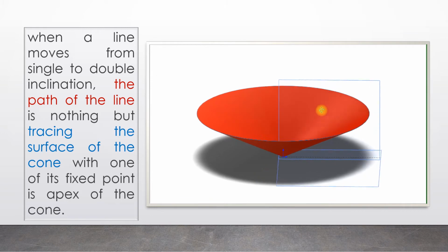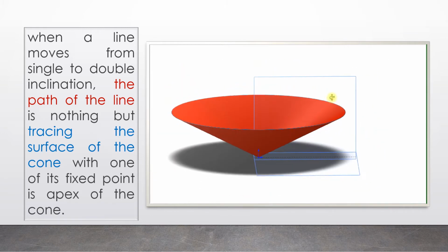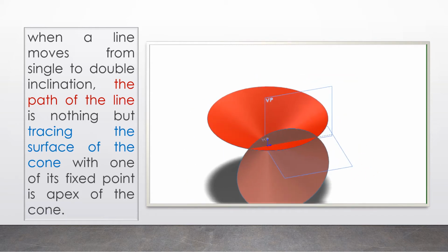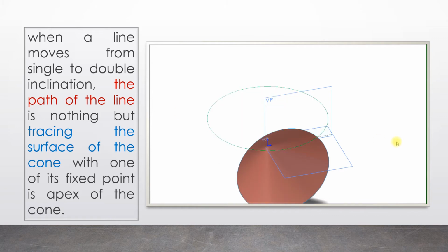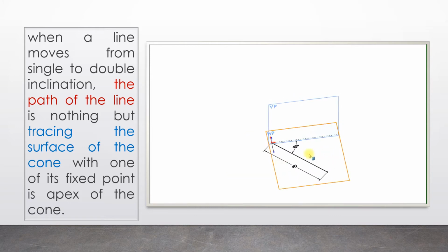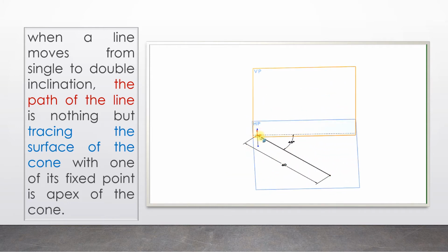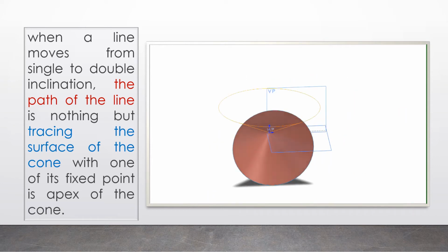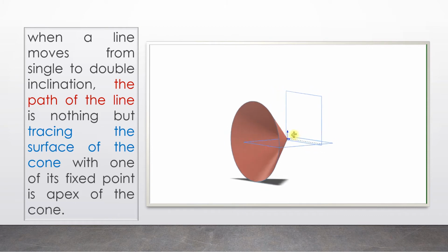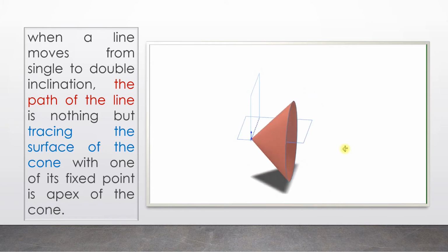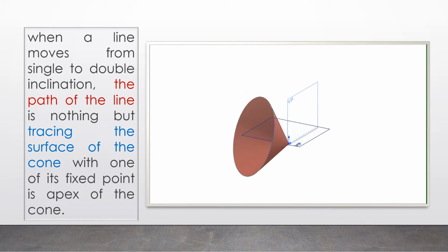Likewise, imagine another cone whose axis is perpendicular to this one. This one means it is perpendicular to VP; the earlier one was perpendicular to HP. So the generator of this cone maintains some constant angle with respect to VP, but the generator of the cone varies with respect to HP, so the inclination will be varying. So the common generator between these two cones, which have been drawn for particular cone complementary angles, will be the line inclined to both the planes.